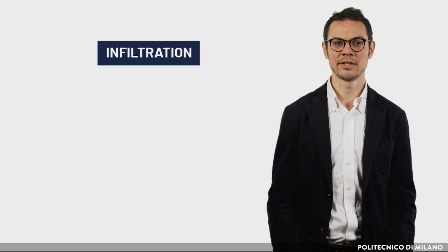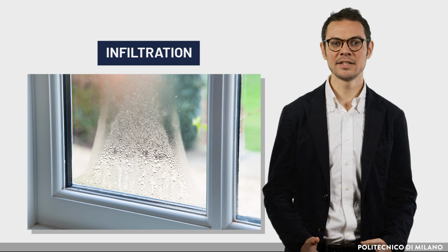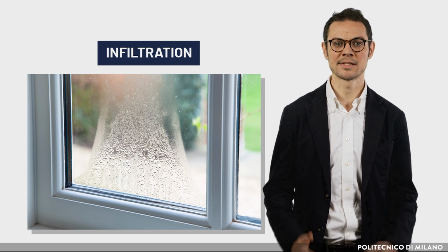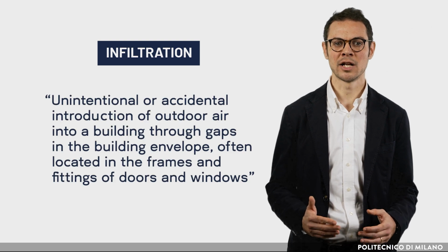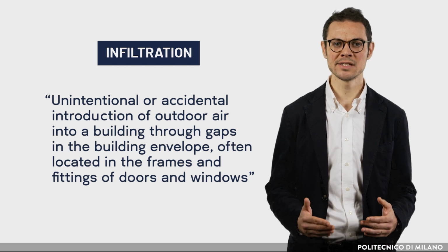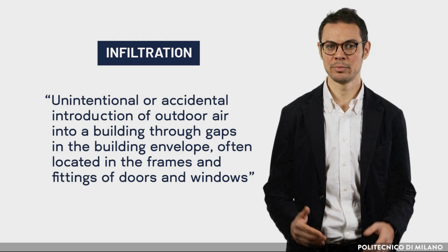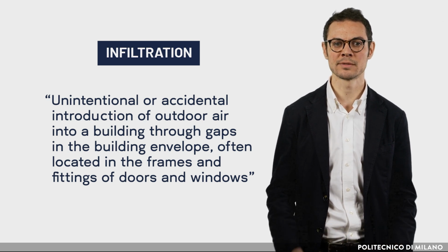One of the major difficulties in the simulation is the possibility to identify a reliable input value for the infiltration rate. Infiltration rate has consequently been ranked as one of the key variables affecting the accuracy of simulation results. Infiltration, in fact, is defined as the unintentional or accidental introduction of outdoor air into a building through gaps in the building envelope, often located in the frames and fittings of doors and windows.